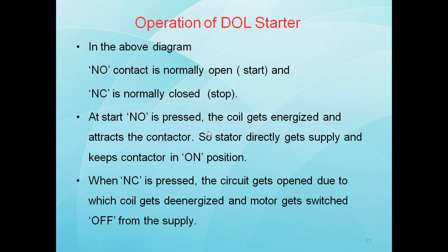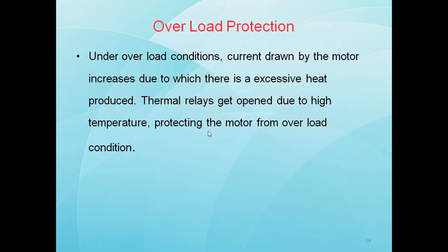When there is no current through that coil, the coil gets released, it opens the switch, the supply is off and the motor is off.